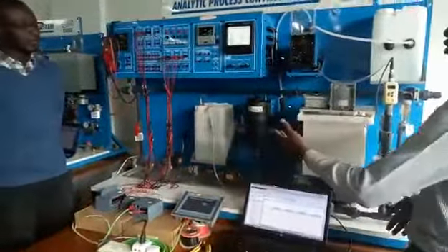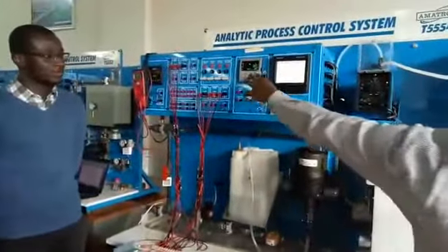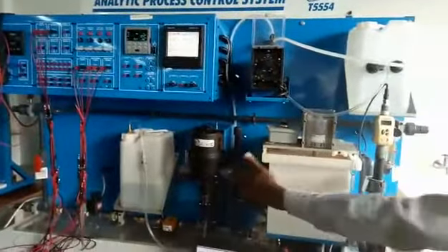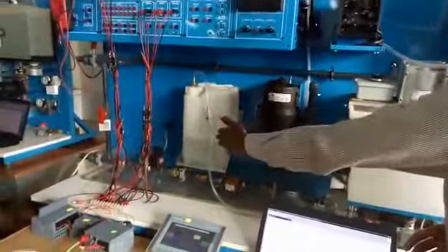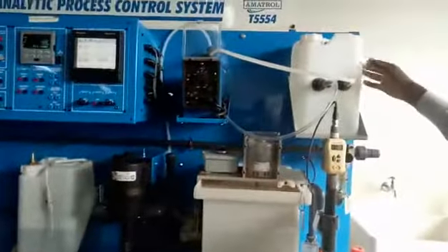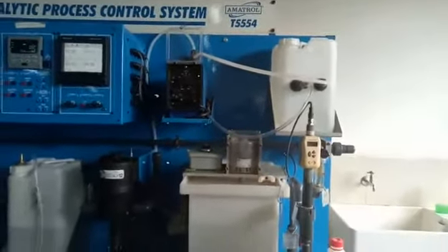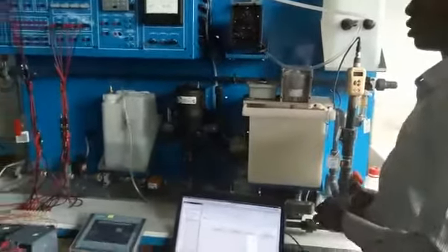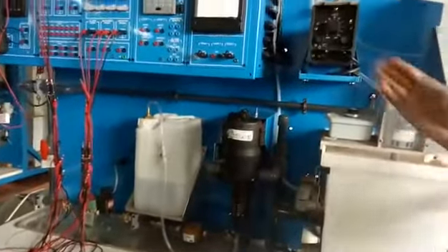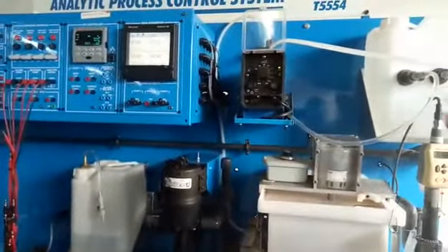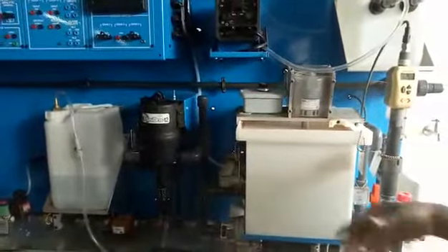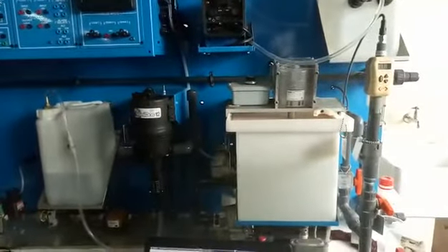To start with, we have the control system panel, which has a PID controller in it. Then, as you can see, we have three different tanks. The first tank here is called the pH reducer, which contains a low pH solution. Then we have the riser tank, which has the high pH solution, and then we have the mixing tank here. Then we've got the inductor pump, which pumps the lower pH solution into the mixing tank. We have the metering pump, which pumps the higher pH solution into the mixing tank. Then we have the agitator motor, which mixes the two solutions in the tank to control the pH.